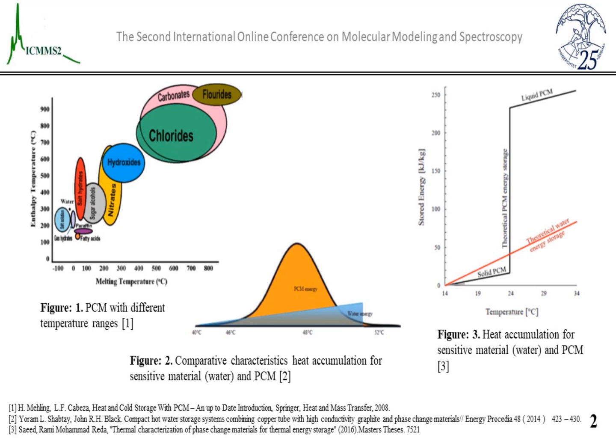The diagram presented in Figure 1 shows the entire list of materials potentially suitable for heat storage. Sensible materials such as water have a much lower heat capacity, which is illustrated in Figures 2 and 3. Among the proposed materials, salt hydrates are the most effective due to their optimal working temperature characteristics, ensuring operability in temperature ranges close to room temperature, that is from 0 to 100 degrees Celsius.